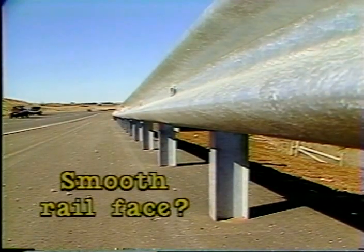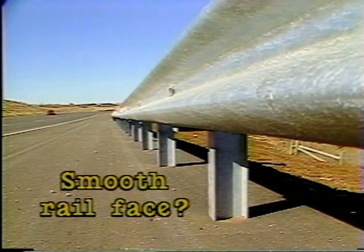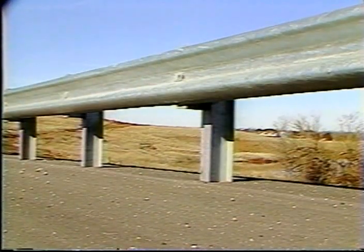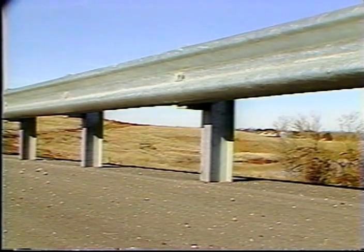Is the rail face smooth? Are splices lapped in the direction of traffic flow? Are post connections properly installed and tight? And finally, do the rail's support posts or other elements show any signs of corrosion or damage? If so, have you taken corrective actions?